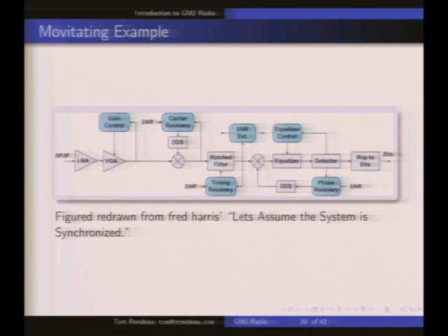Well, if I'm going from here down, that's not too big of a deal because of our digraph concept in GNU Radio. If I want to go from here back, that's a feedback loop all of a sudden, and we don't handle that, and we don't want to handle that. So we've introduced two ways of rethinking a control plane in GNU Radio. They haven't been publicized too much. There's not a whole lot of code that actually shows them working, but we're working on it.